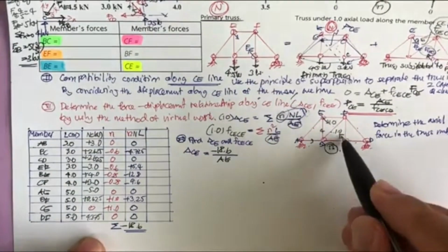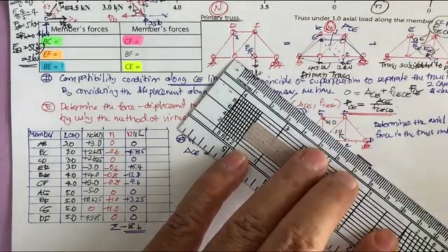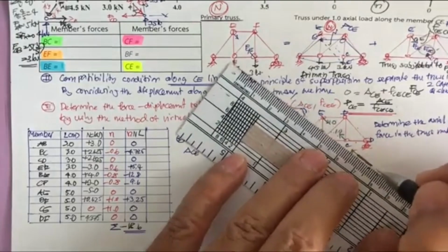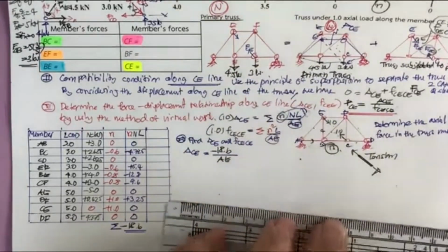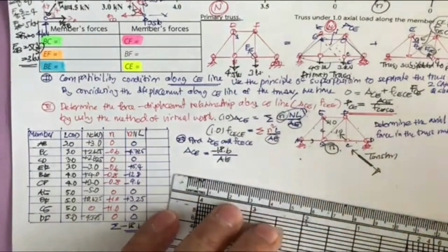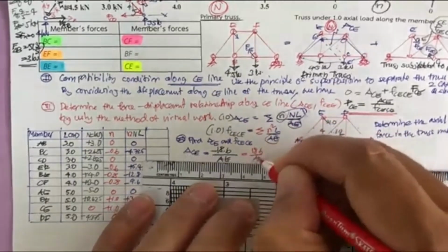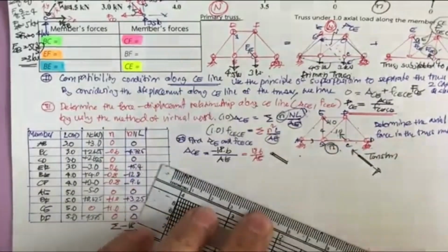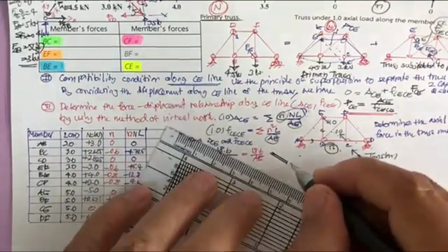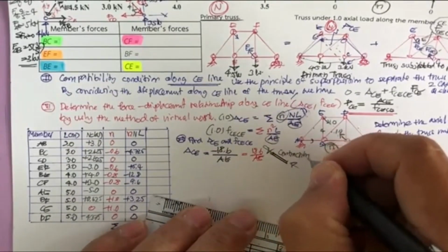That means it is going to be in the opposite direction. If you take this member, the force of 1 unit acts in this member as tension. Since this is negative, the member is going to be in compression, in the opposite of the assumed direction. And this one is going to be in contraction. It's negative.